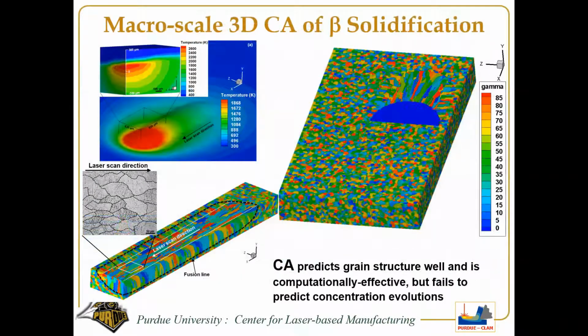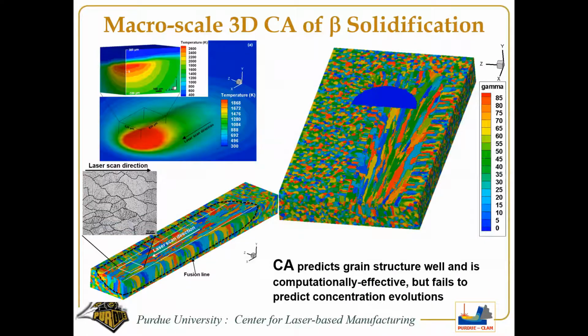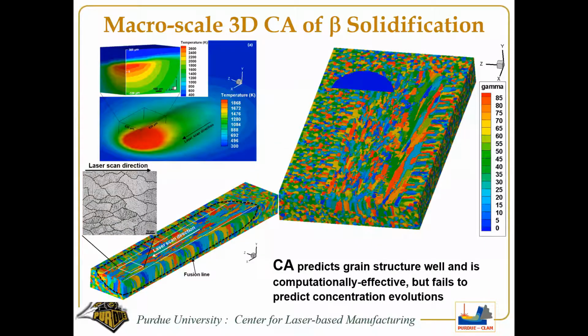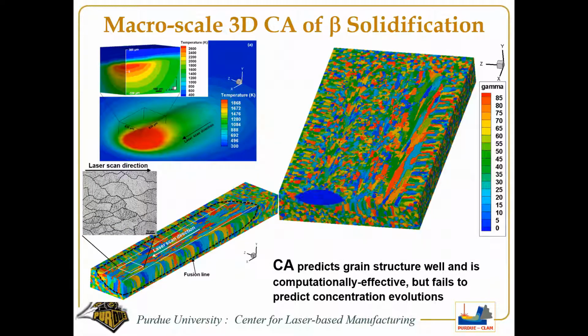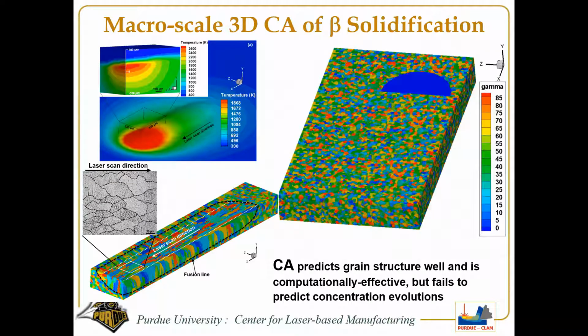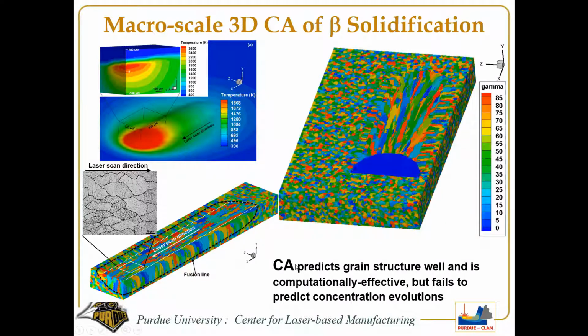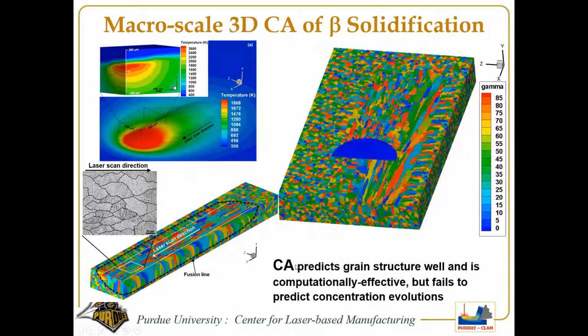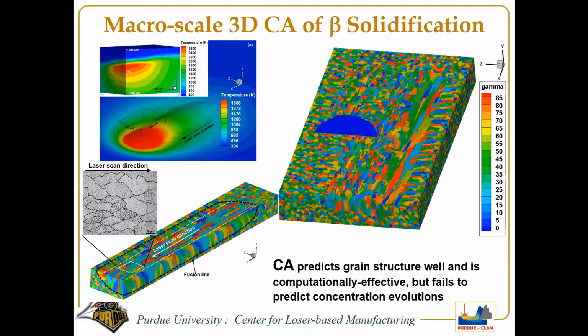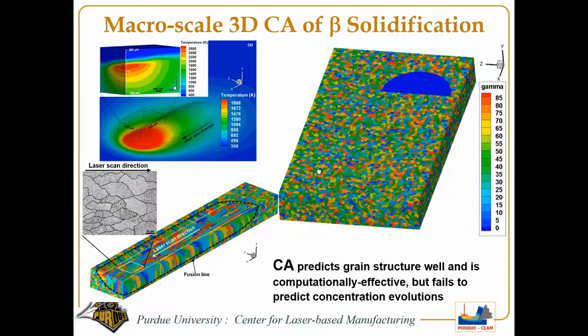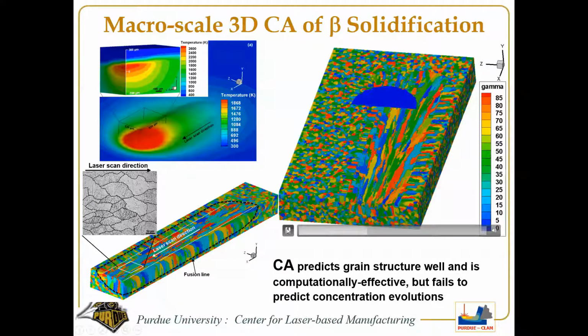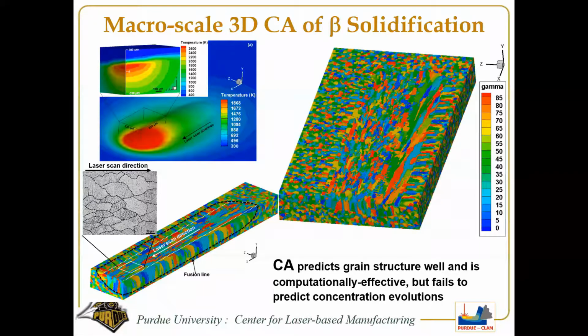The second portion you want to do is, once you get the temperature field predicted, you want to predict the microstructure. So this is another image my students have created. In this case, as a laser beam moves around, and let me see if I can play this video, your grains, you have melting and solidification, so grains get elongated and change directions. And like I said, microstructure affects the resultant mechanical properties. So we need to predict what kind of microstructure you have.